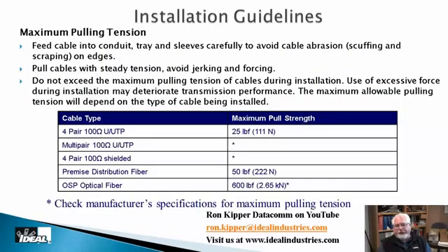Pulling tension is a really good one to ask people about. It's interesting, as far as pulling tension on the cable, what should that be? Well, the best answer to that is go check with the manufacturer who made the cable. They should probably have a suggestion on how to pull it, especially with fiber optic. How do you pull it, obviously with the Kevlar string, not with the fiber. So they might have some tips for you.